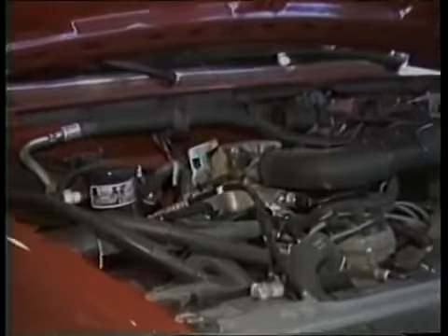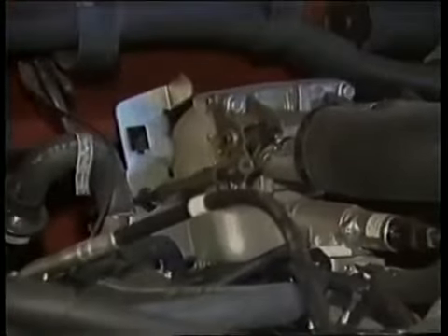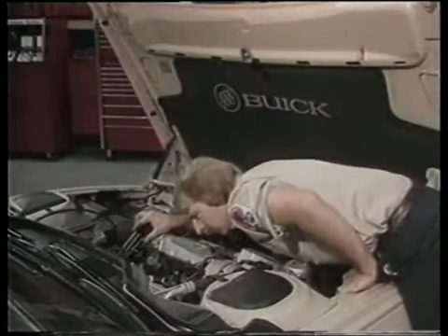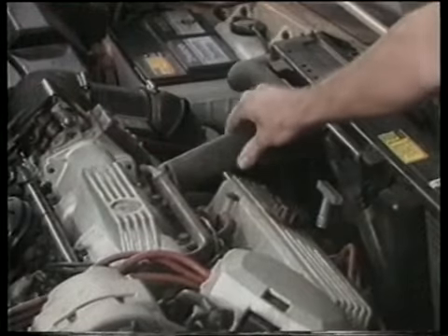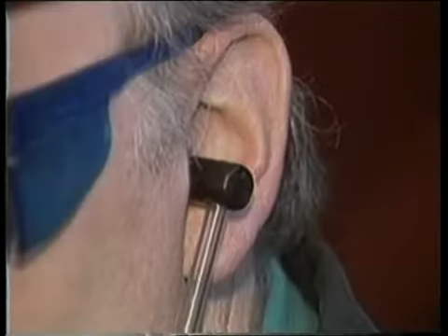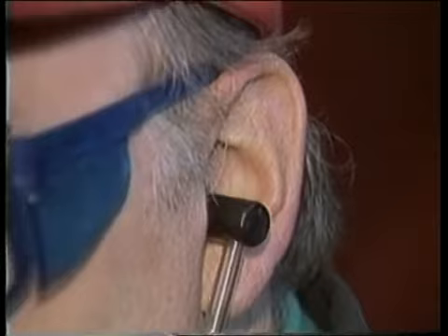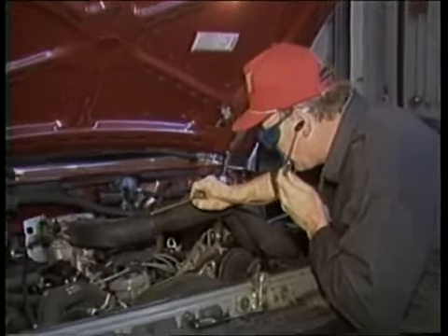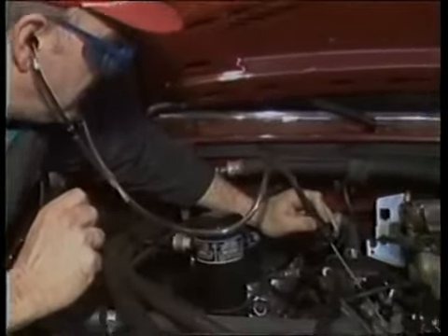Inspection of the engine and related components will sometimes find trouble sources. Check all hoses, wires, and other visible system parts. Look for gasoline leaks, vacuum leaks, kinked lines, loose electrical connections, and other troubles. With all the plumbing under the hood of a modern car, vacuum leaks have become more common and troublesome to locate. You can use a stethoscope with the metal tip removed to pinpoint the hiss of a leak.